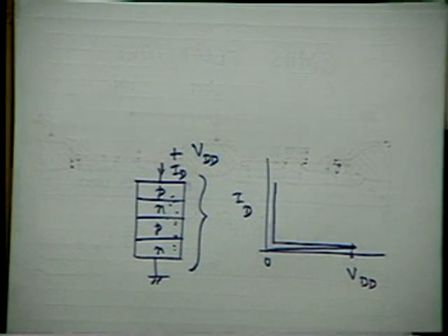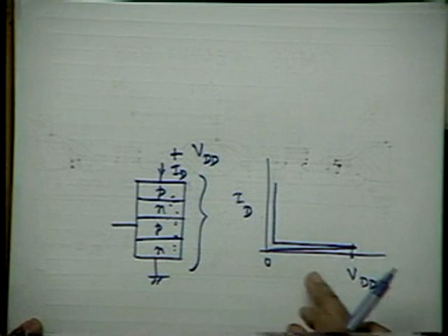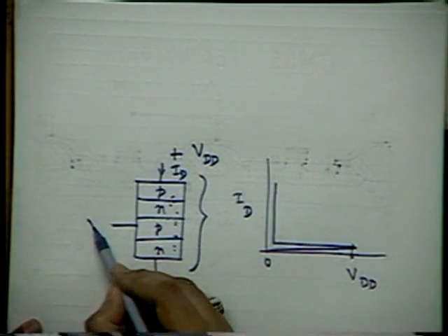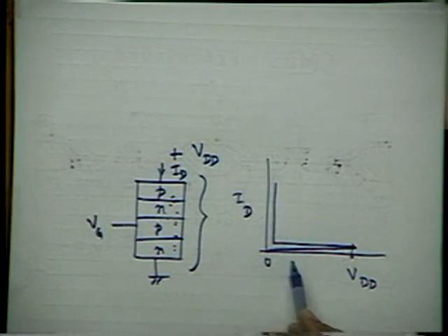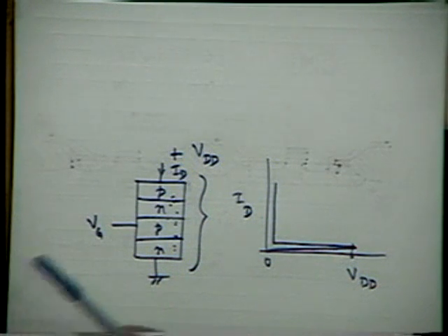And that is a major thing of a thyristor, you know, SCR. And by having a gate, I can influence this process. By having a gate voltage here, you remember that I can have characteristics like this. I can control the switching point. This is what is called latchup.